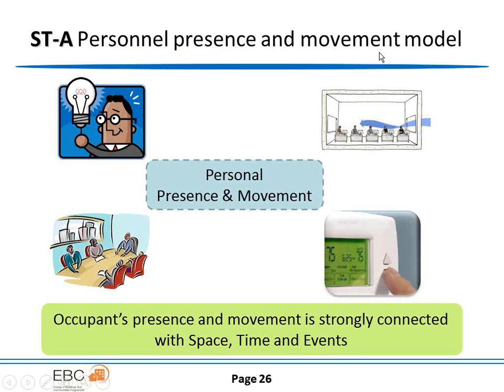I think PG&E is doing this evaluation of VRF systems, right? If you don't have a better way to handle the occupancy, you will not be able to capture the VRF system's performance accurately. Because with VRF, when no one is in the space, you can turn off that system. But in modeling, you can never show a time that a space is unoccupied, so basically it's operating like a VAV system. You don't turn it off. So it's getting more important to model occupancy more accurately. And people's behavior, of course, also depends on whether people are in the space.